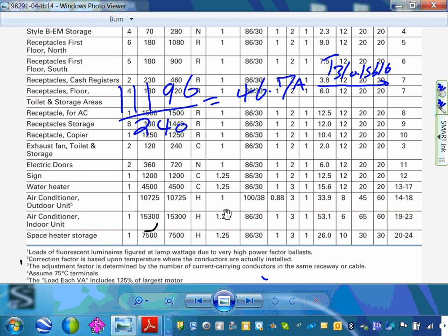Now, this is an AC unit. They must have the lugs rated for 75. Go under the 75-degree column. Number 8. Is the number 8 an option? Yeah. Because it's an AC unit, they must have said the lugs are rated for 75. Otherwise, if they don't say that, what do you use? 60. Okay. Number 8. Everybody's good with that?